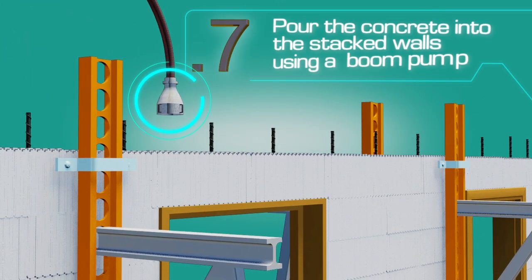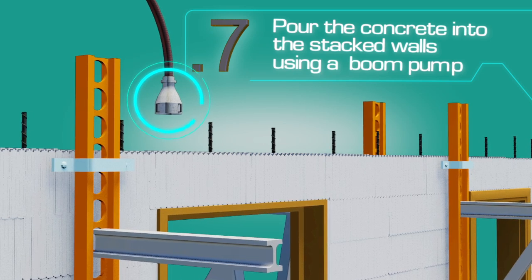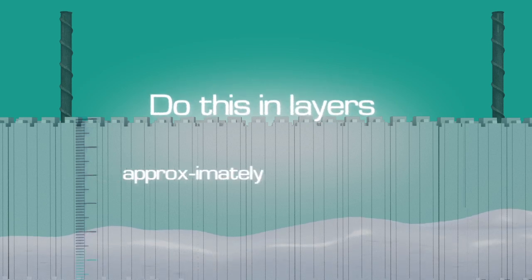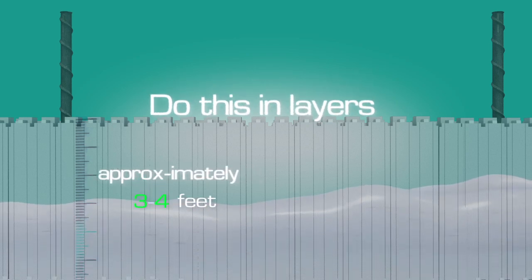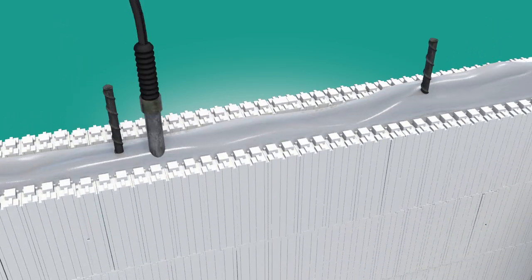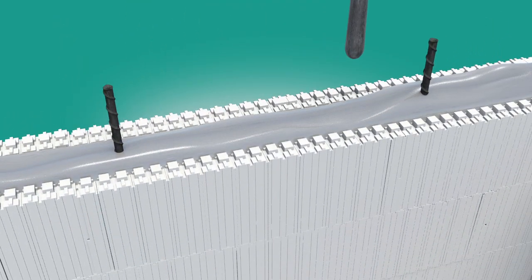Pour the concrete into the stacked walls using a boom pump. Do this in layers, approximately 3 to 4 feet at a time, circling the structure until the top of the wall is reached. Next, use a mechanical pencil vibrator to vibrate the concrete and remove all air pockets within the wall.